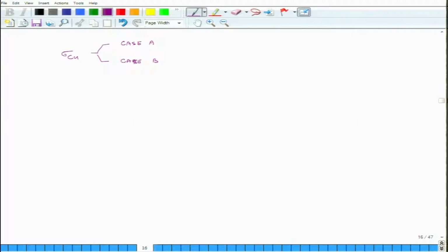If those assumptions, which we will very quickly discuss now, are not necessarily true, then the calculation of sigma Cu based on case A and case B may be an upper limit, but real values will be somewhat lower. So, what are the assumptions which we assumed and never explicitly stated?